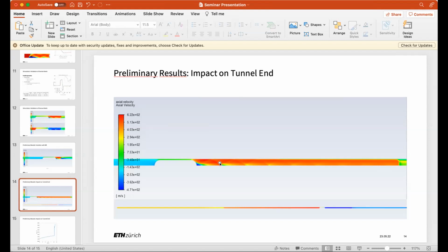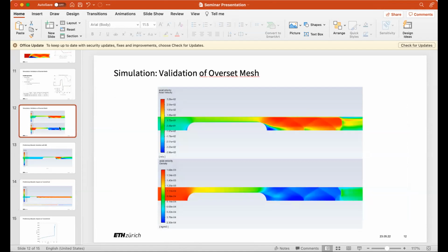Okay, then somebody would like to know what have been your boundary conditions to conduct your CFD simulations? So at the start, for these validation cases, we had outlet pressure boundary conditions on both the front and the back, and then moved the pod mesh.